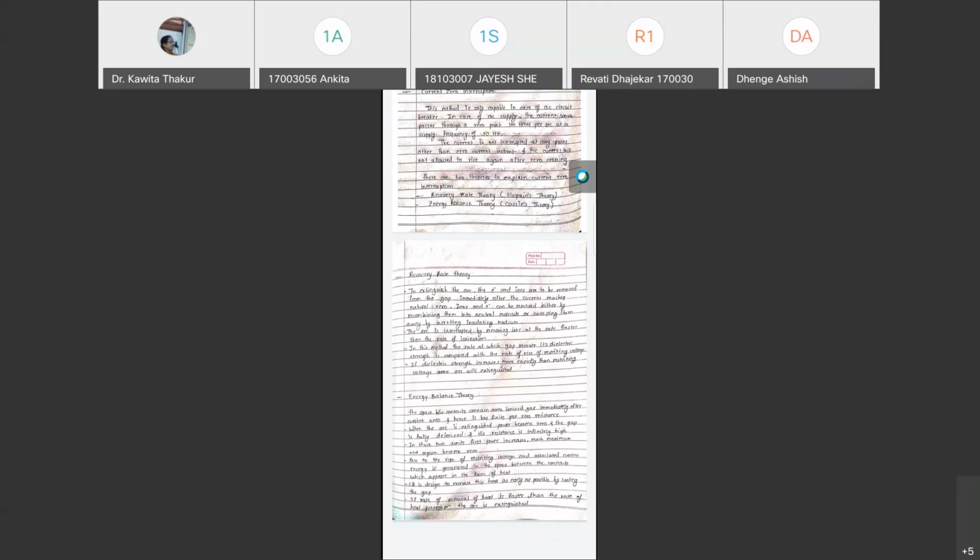These electrons and ions can be removed either by recombining them into neutral molecules or by sweeping them away by inserting an insulating medium. This insulating medium can either be gas or liquid, and the arc is interrupted by removing ions at a rate faster than the rate of ionization.